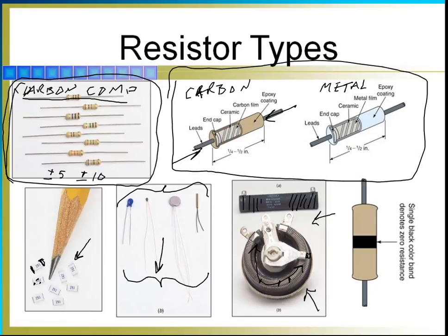And then, of course, you have fusible resistors. Now, this one happens to be a 0 ohm resistor. So when you read it, it has 0 ohms. But when the power gets too big or too much for the size, it's going to open up. So it becomes just like a normal fuse. Otherwise, it's a jumper. So 0 ohm, you've got a black stripe on it. And once again, we're going to look at the stripes in just a moment. So, carbon composition, film type, chip resistors, thermistors, wire wound, and fusible resistors. Different types that we have.